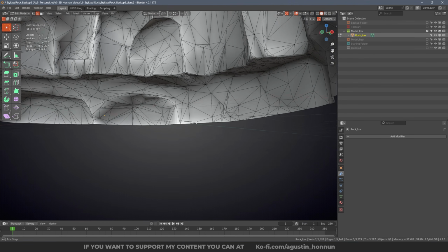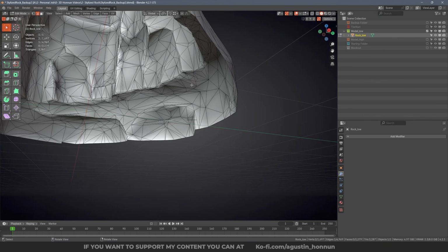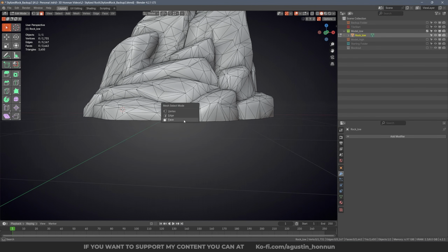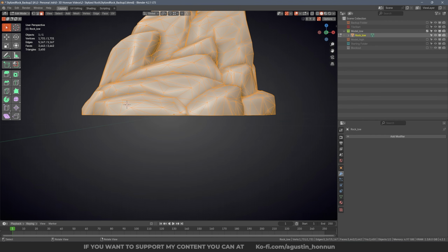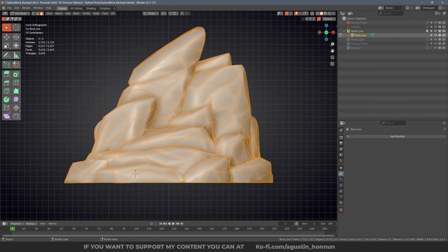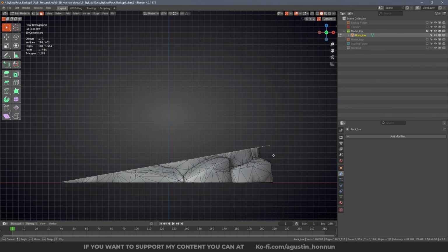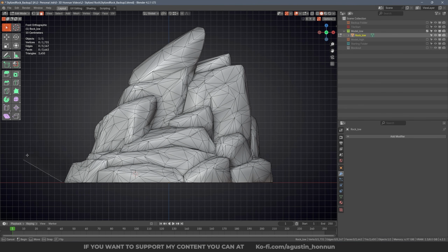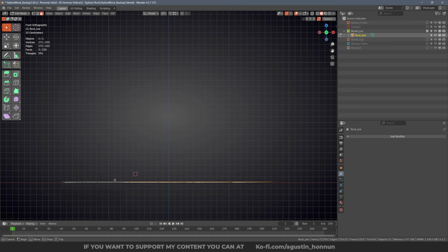As you can see, we have some floating edges. You can remove them manually, but I recommend you use this method. Go to front view, then use the same basic tool that we were using before here, and drag a line here, pressing Ctrl. So you can see, if you press Ctrl, you can move this line.